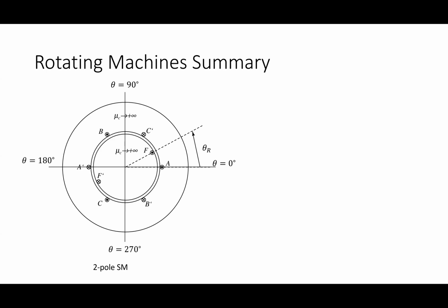Now I can't have a two-phase machine. That will work. If you've ever fixed an air conditioner, you know that there's a capacitor in there, and what the capacitor does is create a 90-degree shift to another voltage, so that there's a two-phase machine when you start it. You can let a single-phase machine run, but it can't start.